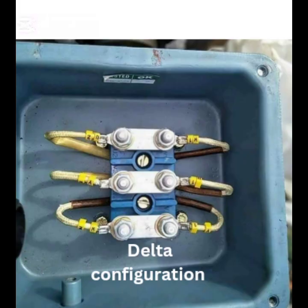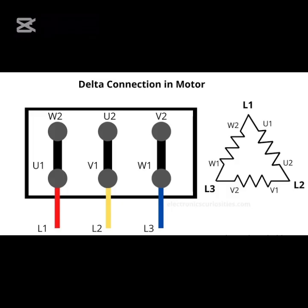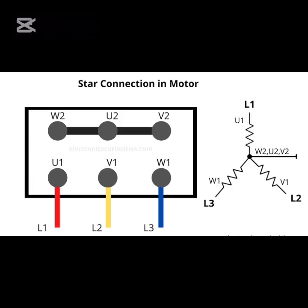6. Neutral point. In delta configuration, no neutral point exists, so it cannot carry unbalanced loads. But in star configuration, a neutral point is available and can be used for grounding or carrying return currents in case of unbalanced loads. 7. Starting characteristics. Delta winding is better for starting high-torque motors as it provides high starting current, but star winding is typically used for reducing starting current. Star-delta starters are used to prevent inrush current.